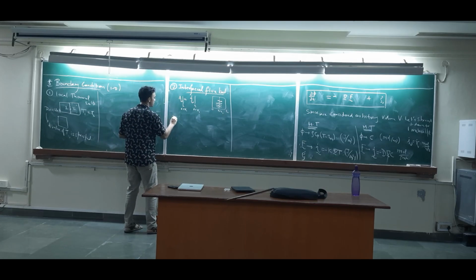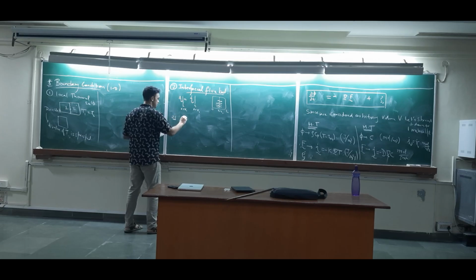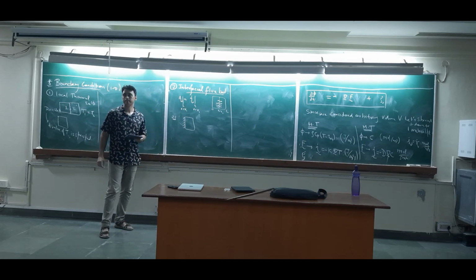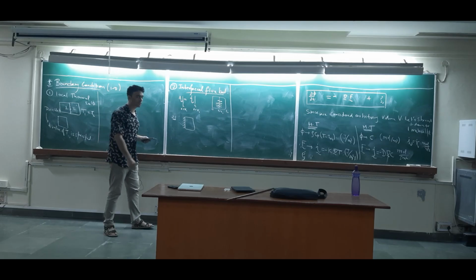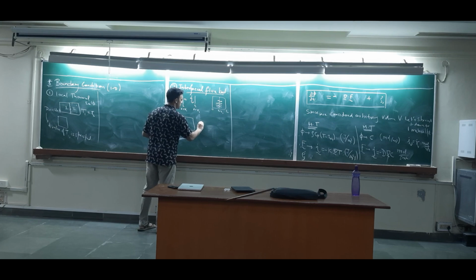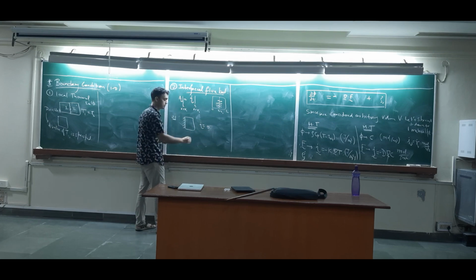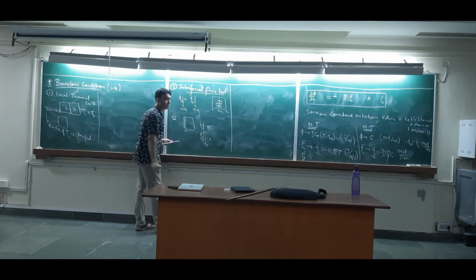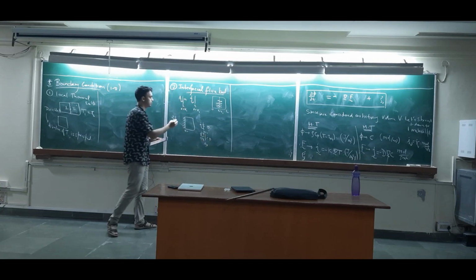Another type, if I can write, is this. You must have seen it n number of times. What are these dashed lines? Insulation. So what is the flux? Flux is 0, right? So Q dot is 0, meaning dou T by dou X at X equals 0 is 0. So temperature profiles always make some sort of 90-degree angle here.